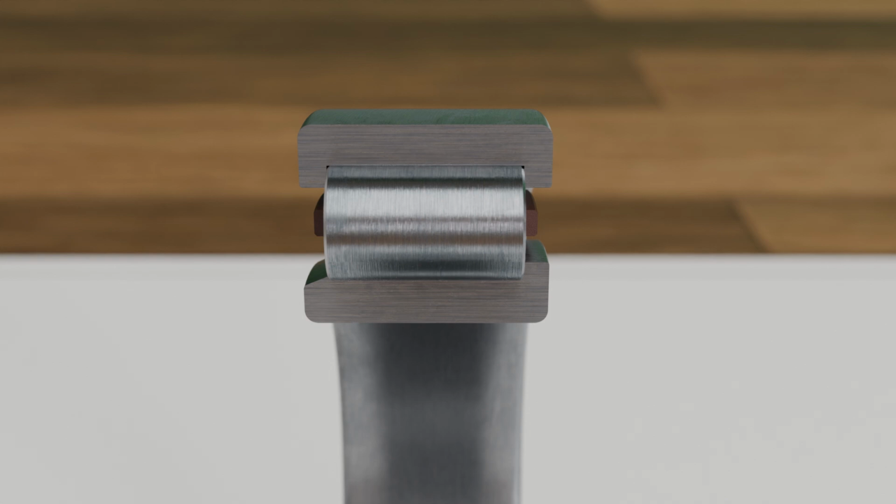Another bearing design is the NUP cylindrical roller bearing, which provides axial guidance in both directions. The inner ring has a fixed flange on one side. On the opposite side, a separate loose flange ring is supplied. This flange ring is pushed onto the inner ring during assembly and acts as a second flange. As a result, the bearing is axially fixed in both directions. The combination of a fixed flange and a loose flange ring allows for easy installation, especially in cases where the bearing seat is difficult to access or when the shaft is inserted through the bearing first.